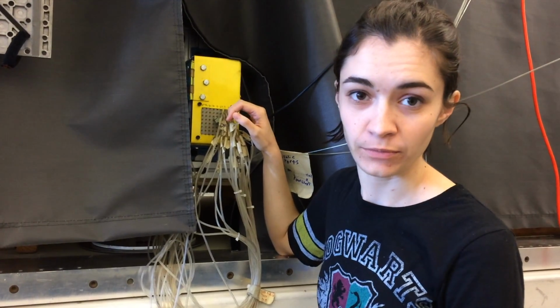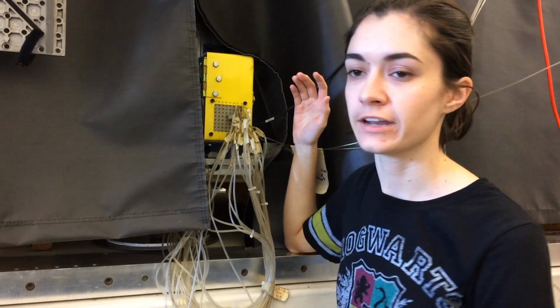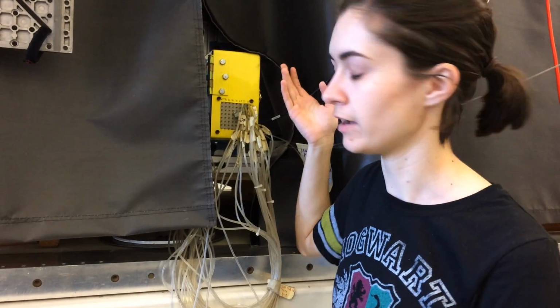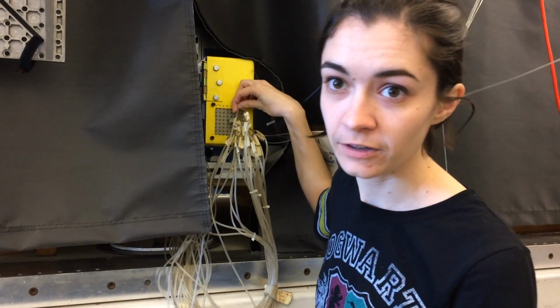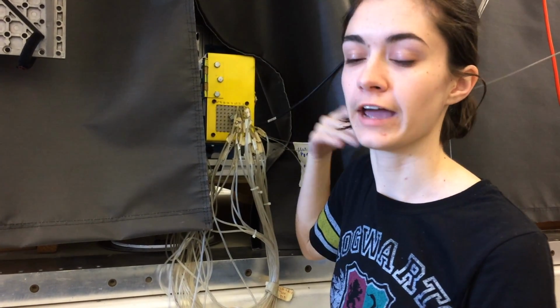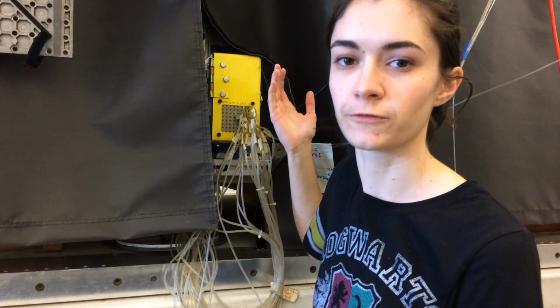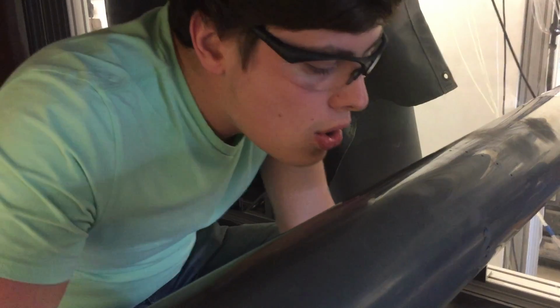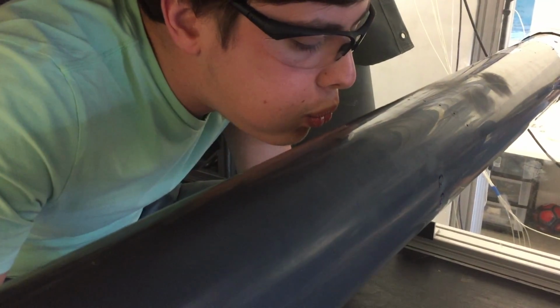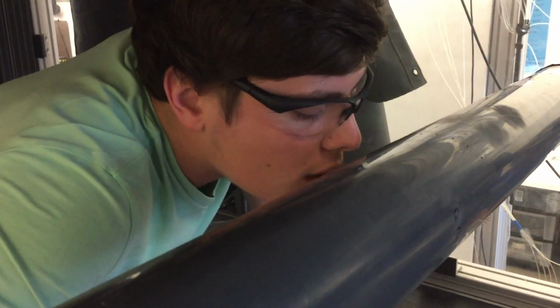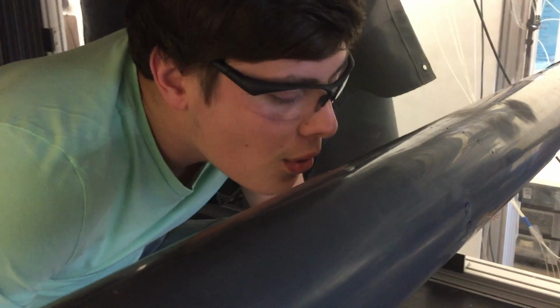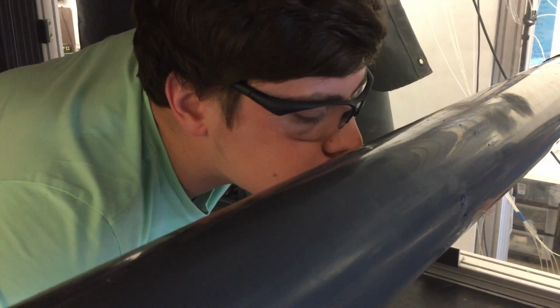One of the issues that we ran into while we were doing our testing had to do with the pressure ports reading the incorrect data. They needed to be plugged in properly in order to get the data that we were looking for and to give us correct coefficient of pressure graphs. While troubleshooting why we weren't able to get correct pressure data on all of our pressure taps, we had to blow into the pressure taps individually to check to see which ones were working.